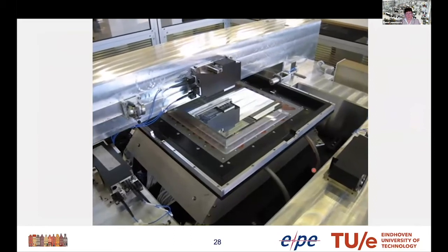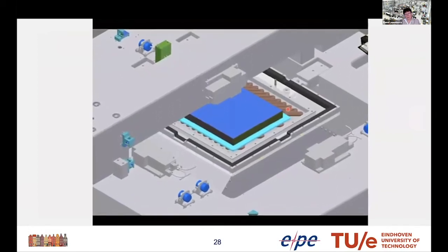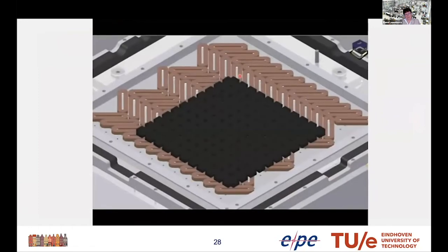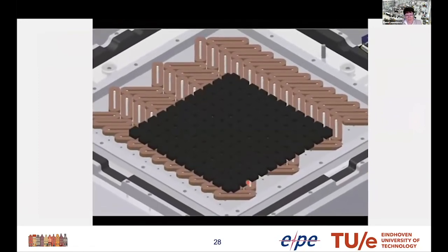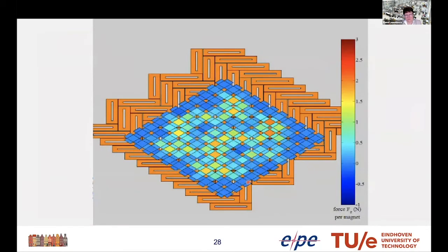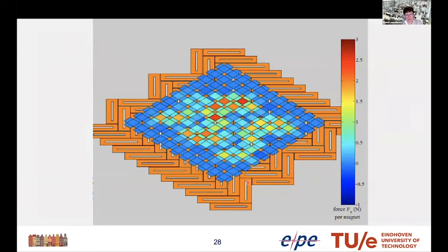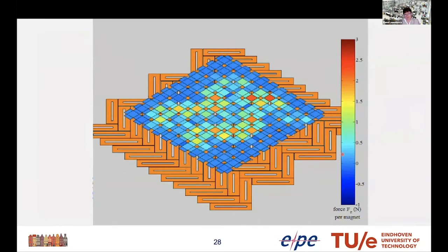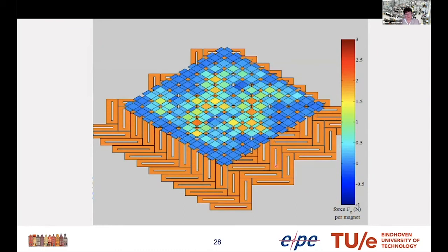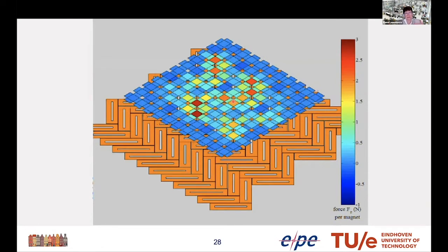The next generation of planar motors is realized over here, so we can see the assembly of the structure, or zoom in on the arrangement of the configuration. It's still herringbone coils with the magnet plate assembly on the top of that, and the movement or performance of the planar motor can be easily considered here with the recognition of the forces acting from individually powered coils on the top of the permanent magnets, which exactly shows the heterogeneous character of force distributions on the structure.